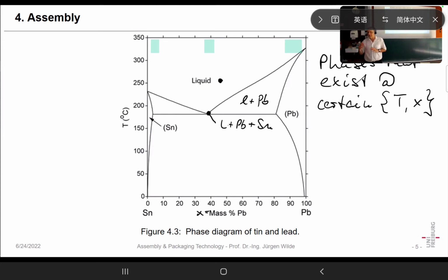your proposal was also correct insofar as a phase diagram is normally not made by just going to one temperature and composition, but rather by finding out what are the transition points or lines. Yes. So we cool, for instance, a certain composition and look.